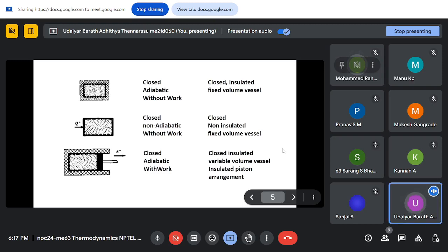So now we have seen, we'll see in brief what we can say. I have listed out some examples of this closed and open system. If you see the first one, we have a fixed system, and the outer box with the cross hatches specifies an insulation. Insulation in this case means no heat transfer can happen. There is no mass transfer happening, and this is insulated, and there is no work happening. So the system is a closed one.